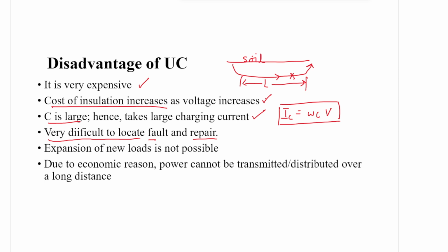As long as it is going below the soil, it is extremely good; 99.99% of the time it runs extremely smoothly. However, unfortunately, if some fault comes at any point of length or time, it becomes extremely difficult to locate and repair. If you want to repair, you need to dig up the soil, so it is a loss of resources, loss of money, everything.